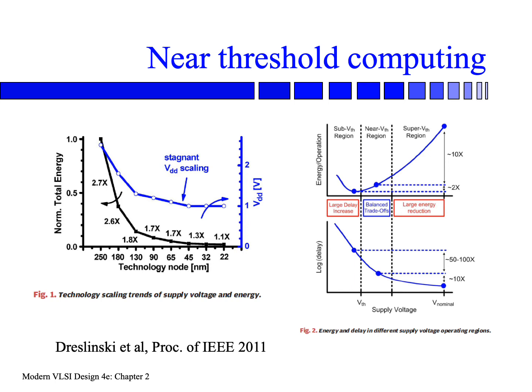Yeah, so in other words, you pretty much don't gain anything after you reduce the supply voltage beyond the threshold voltage. So people argue that probably the best trade-off will happen in the so-called near-threshold region. We still keep the energy pretty low, and the delay is not significantly large. So the energy-delay product still wins. That's why this whole design strategy is called near-threshold computing.